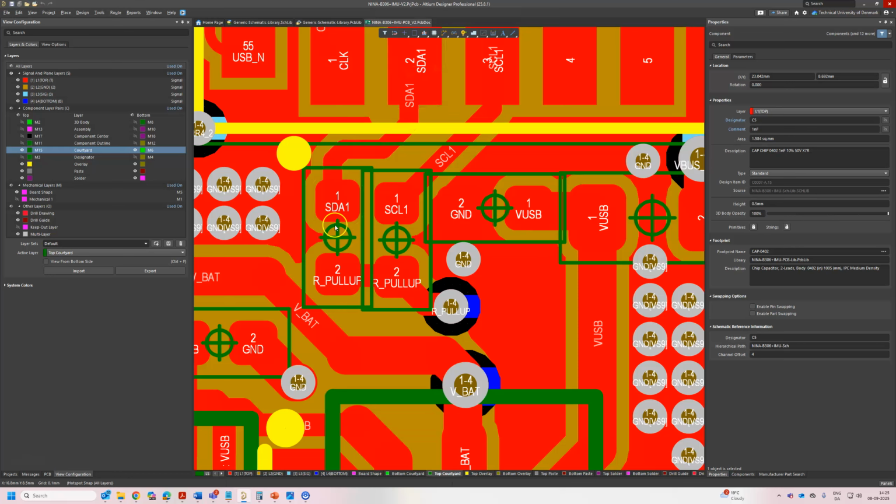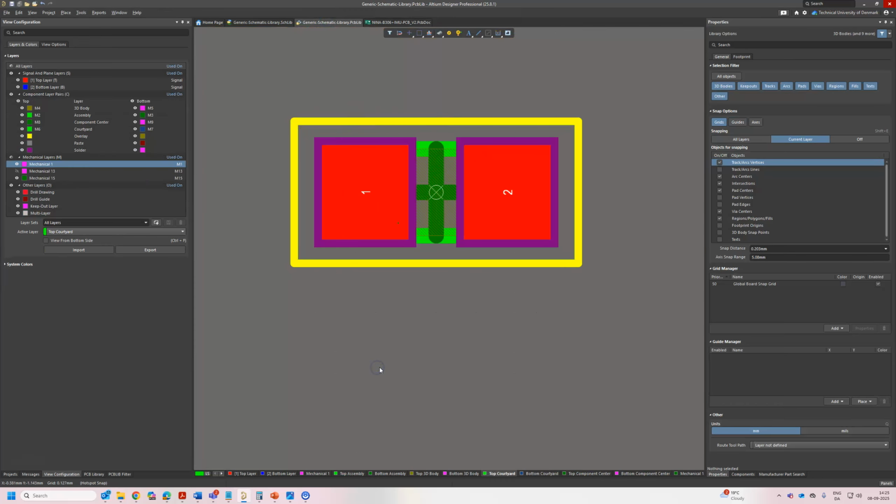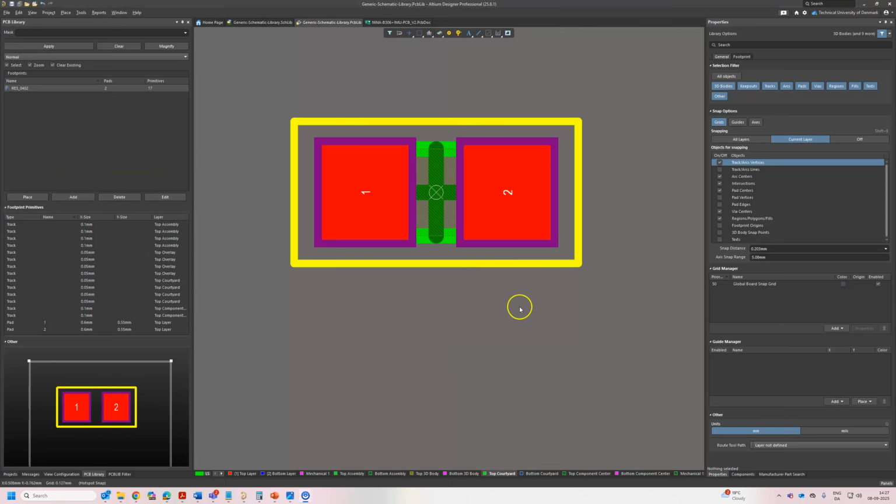So if I have this center here, then I will know immediately my component here has pin 1 here and pin 2 here, and it's this one. It's also not something that will be printed or that the manufacturer needs, it's more for you. Then Control S. So now I have all the layers I needed for my footprint.